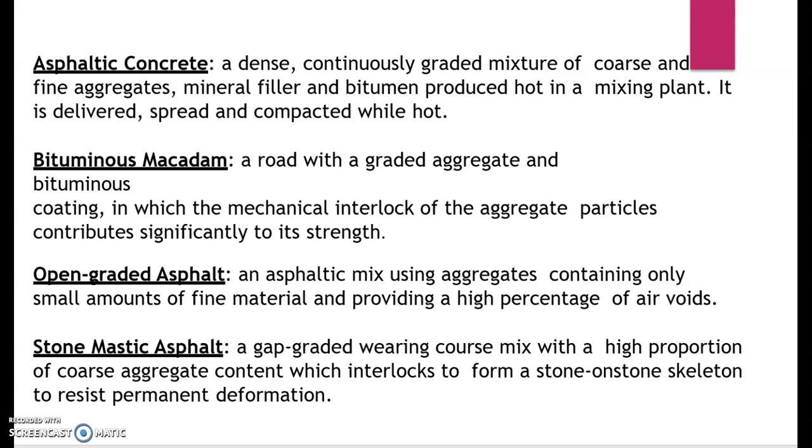Then bituminous macadam, a road with graded aggregate and bituminous coating in which mechanical interlock of the aggregate particles contributes significantly to its strength. Then you have open graded asphalt, an asphaltic mixture using aggregates containing only a small amount of fine material, providing a high percentage of air voids.